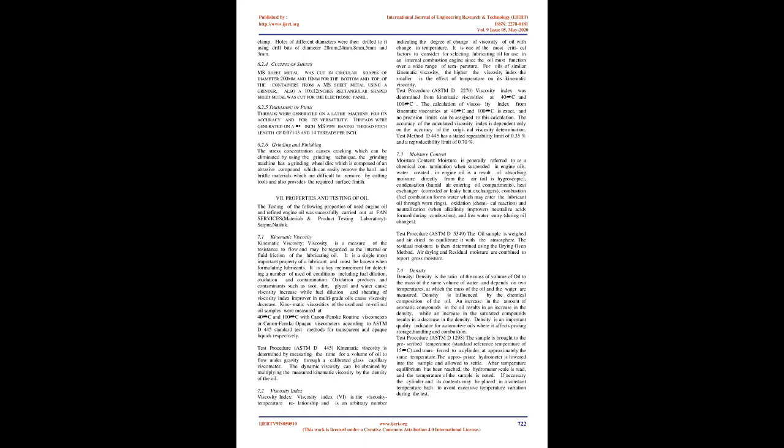7.1 Kinematic viscosity. Viscosity is a measure of the resistance to flow and may be regarded as the internal or fluid friction of the lubricating oil. It is a single most important property of a lubricant and must be known when formulating lubricants. It is a key measurement for detecting a number of used oil conditions including fuel dilution, oxidation, and contamination. Oxidation products and contaminants such as soot, dirt, glycol, and water cause viscosity increase, while fuel dilution and shearing of viscosity index improver in multi-grade oils cause viscosity decrease.